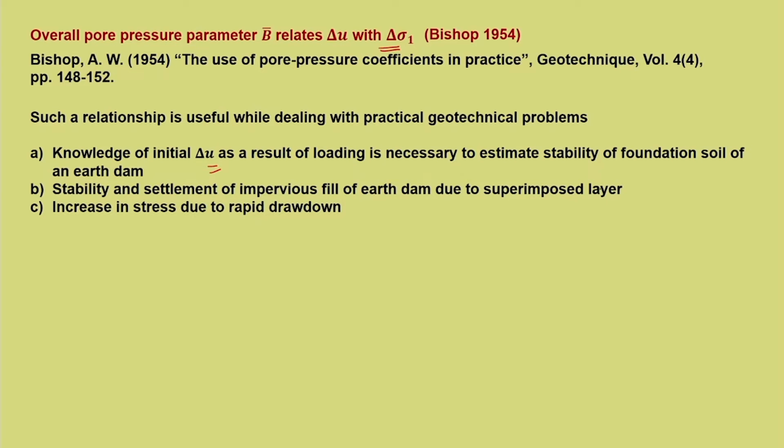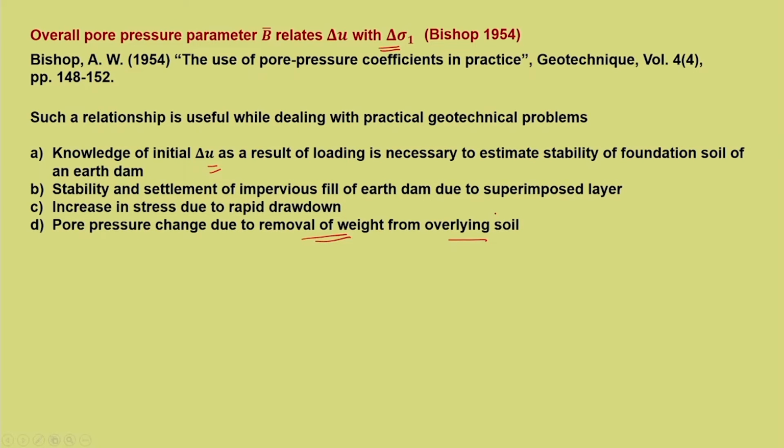It is not only that you are adding water to it, but when there is immediate release of water from the soil, the effective stress increases. Due to this effective stress increase, there will be a kind of settlement. So, that issue is relevant with rapid drawdown. Another case is pore pressure change due to removal of weight from overlying soil. What will be the pore pressure change due to release, that is, when we are removing the weight? What happens during that time to pore water pressure?